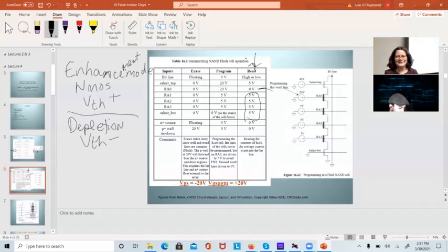The way we fixed this, and it was a horrible argument that I got into, but I had to jump up and down and stamp my feet for quite a while, is basically I got the audio logic guys to agree to power up my negative power supply first. So when you powered up the phone, that was the first voltage that came up. Then everything else lit up on the phone. They weren't happy with that, but they have to live with it. It was either that or blow up lots of MESFETs.